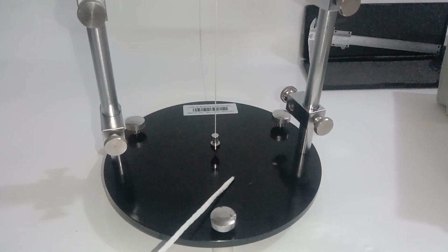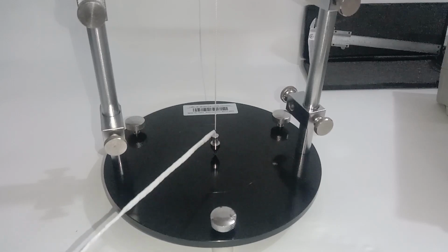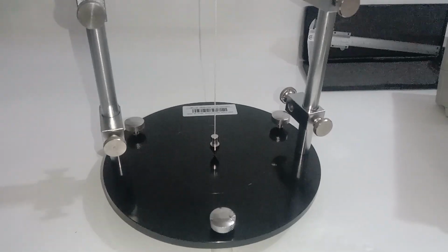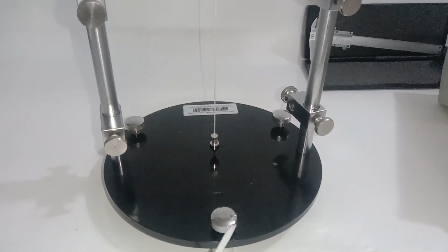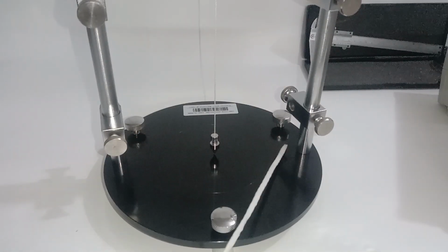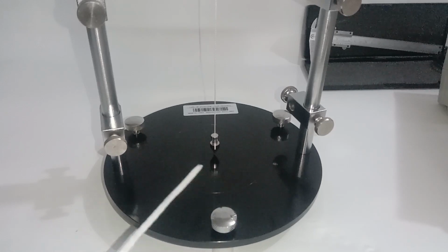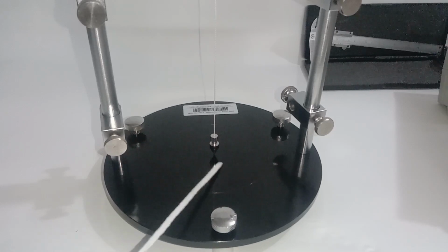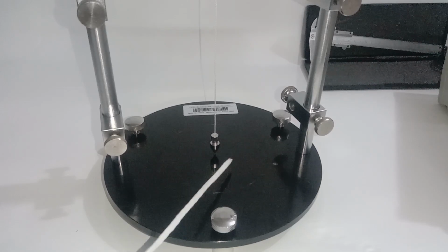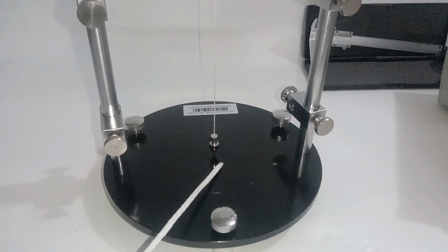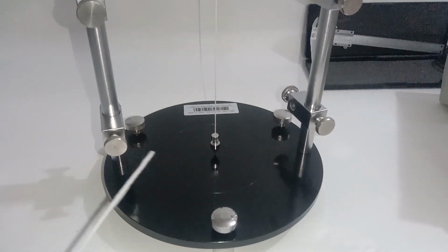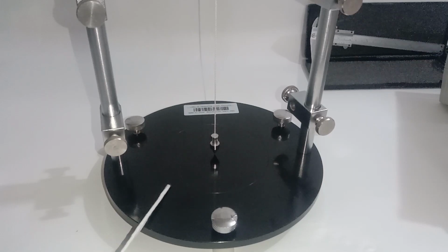But keep this thing in mind that this hammer should not touch the bottom plate. Adjust these three horizontal screws on the bottom plate such that the tip of the hanging hammer aligns with the center of the bottom plate round point. At this time, the test frame is basically vertical.